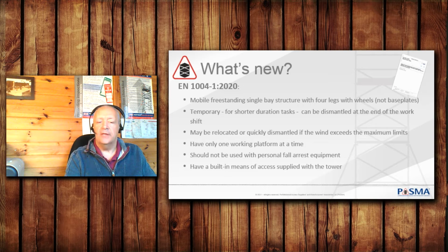This now confirms that other configurations of tower, such as non-mobile towers on base plates, link towers, towers with bridges, large deck structures, and towers for longer duration, are outside of the scope of EN 1004. These may be covered in the Codex, which we'll touch upon later during this presentation.